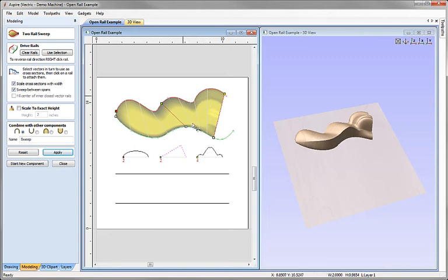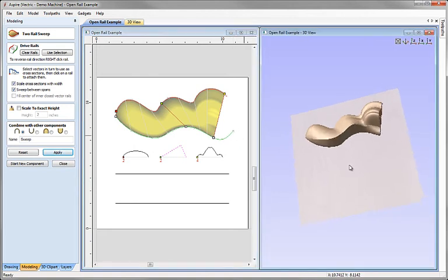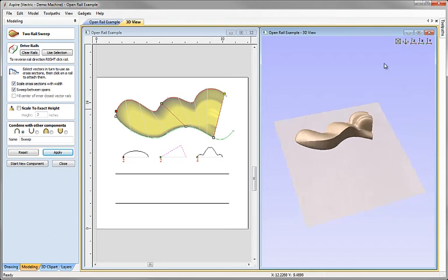These lines give you a good idea as to the flow of the shape, and at the end here, even though we're not going all the way to the end of our vector, the shape we're creating is still stopping between the last 2 points that define the position of that cross section. So you've really got a lot of control over the shape you're creating when using this function, by creating the different vectors and having this ability to insert and reposition the cross sections along the rails.